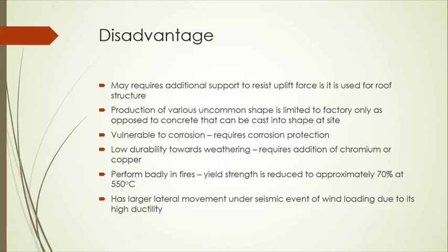And also steel is vulnerable to corrosion, which requires corrosion protection. Either you have cathodic protection, or painting, or you use steel alloys. Steel also has low durability towards weathering, which requires the addition of chromium or copper to protect from acid attacks from weathering.